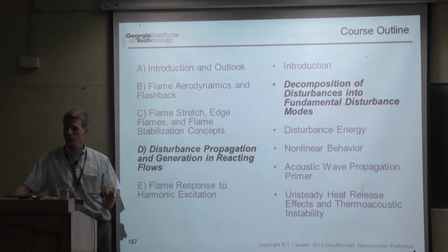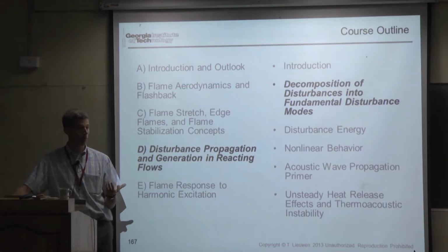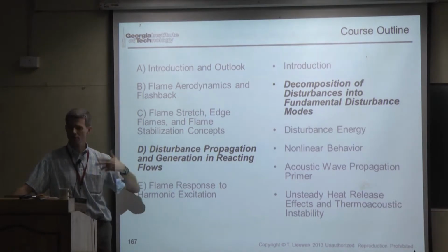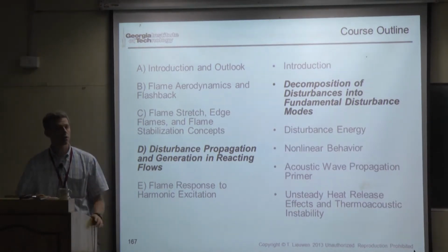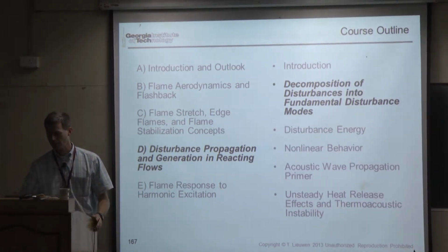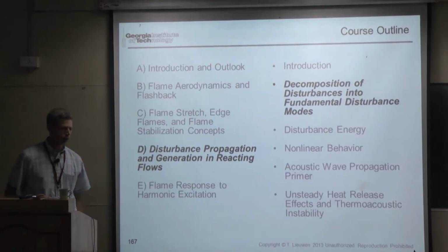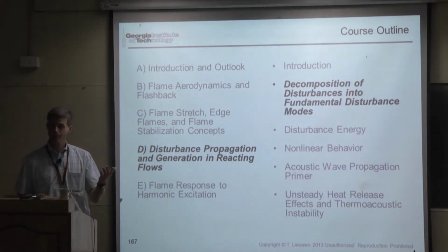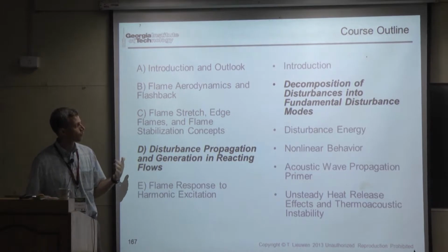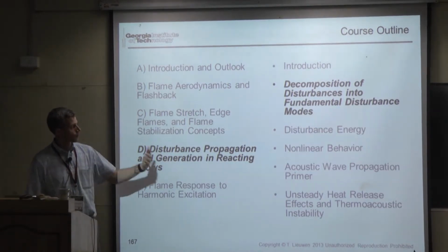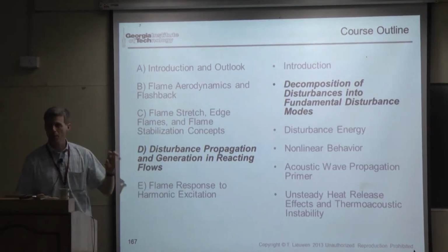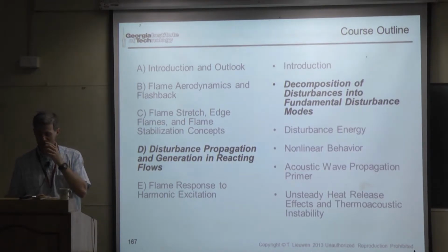So you have shear layers. These flows have shear layers. They're unstable already without acoustic excitation. But now you have these acoustic modes bouncing around. They're exciting these shear layers. You have the potential for, the flame is generating entropy, but you have the potential for the temperature after the flame to be getting modulated, which are what we call entropy disturbances.